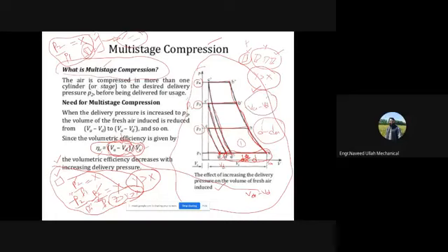So you can see that increasing pressure ratio, the induced volume is decreased for the same initial pressure. तो आपके पास क्या होगा कि ये swept volume is the same, the clearance volume is the same, and by increasing the pressure ratio in the same single stage or single cylinder reciprocating air compressor, the induced volume decreases, ठीक है, ये induced volume decrease होता है.